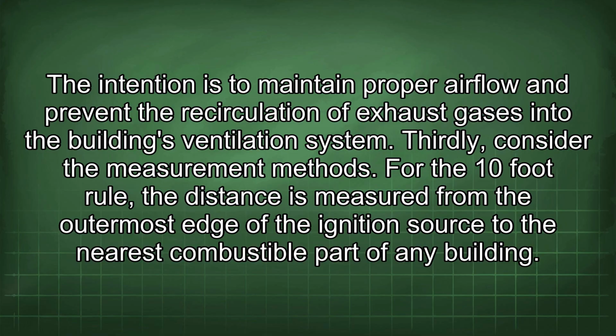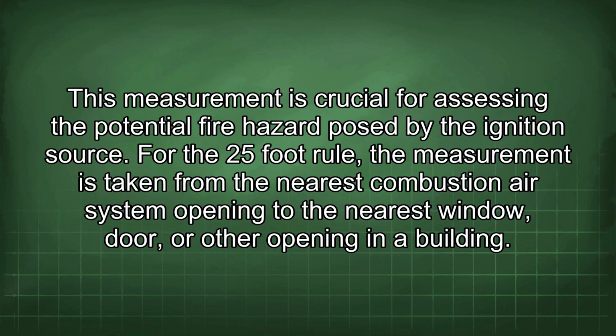Thirdly, consider the measurement methods. For the 10-foot rule, the distance is measured from the outermost edge of the ignition source to the nearest combustible part of any building. This measurement is crucial for assessing the potential fire hazard posed by the ignition source.